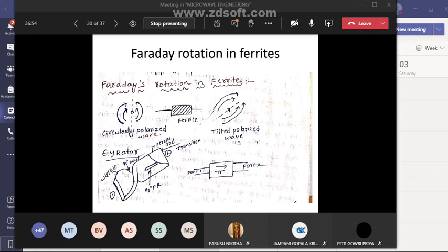When a wave enters at port 1, its plane of polarization rotates by 90 degrees because of the twist in the waveguide. And it again undergoes the Faraday rotation principle through 90 degrees because of the ferrite rod, and the wave comes out of port 2 at a phase shift of 180 degrees.